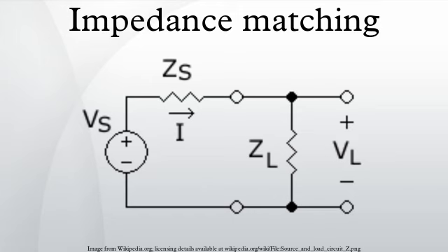The output transformer in vacuum tube-based amplifiers has two basic functions: separation of the AC component from the DC component in the anode circuit of a vacuum tube-based power stage, since a loudspeaker should not be subjected to DC current, and reducing the output impedance of power pentodes in a common cathode configuration.